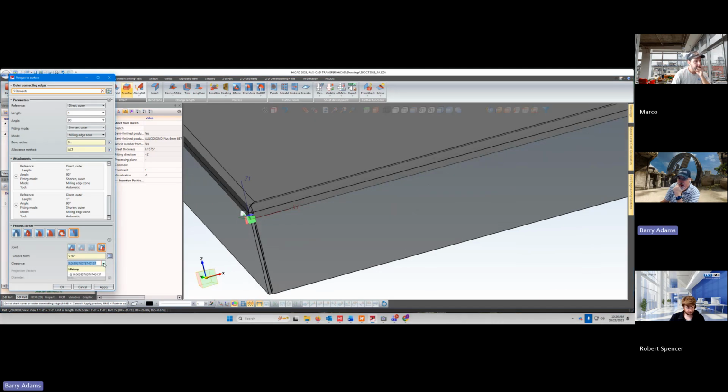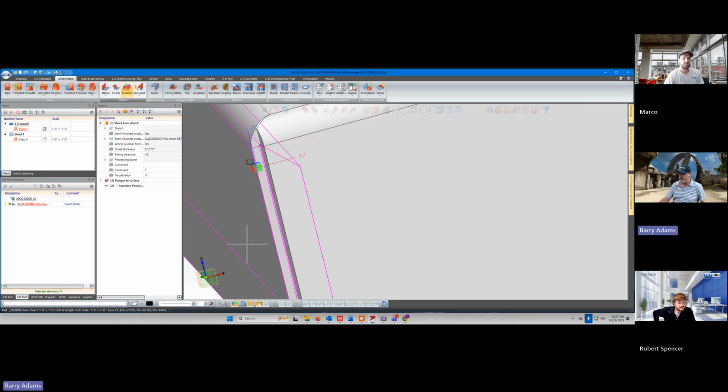That's nice. And that's a little clearance, we allow any value. I usually make it 0, but some customers use that clearance to influence the development result in a certain fashion. I say start with 0. Eventually, you're going to do a test cut, right? See how it comes out, and let's go from there. Okay. Look at that.